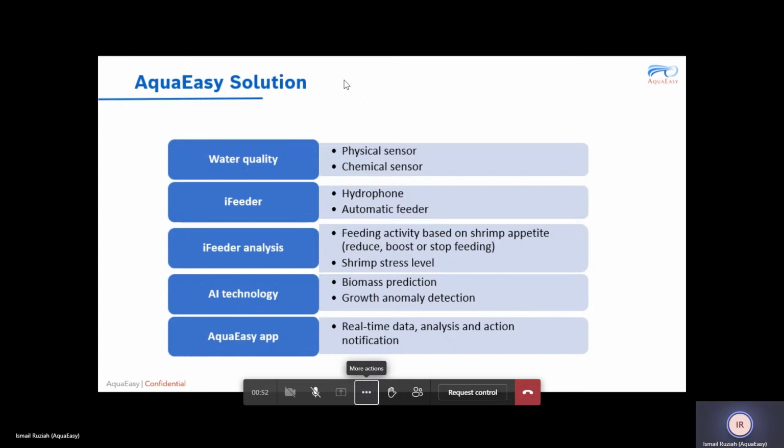And then the other thing which is important is actually the accuracy. We want the dispense rate to be consistent. So standard deviation should not be more than 10 gram. For now, this is still very hard to achieve with wet feed. Dry feed is still okay. So we'll go along with the project or the discussion on this thing.